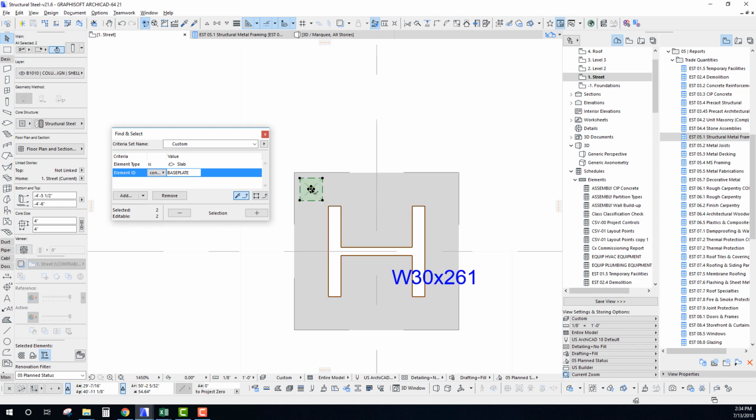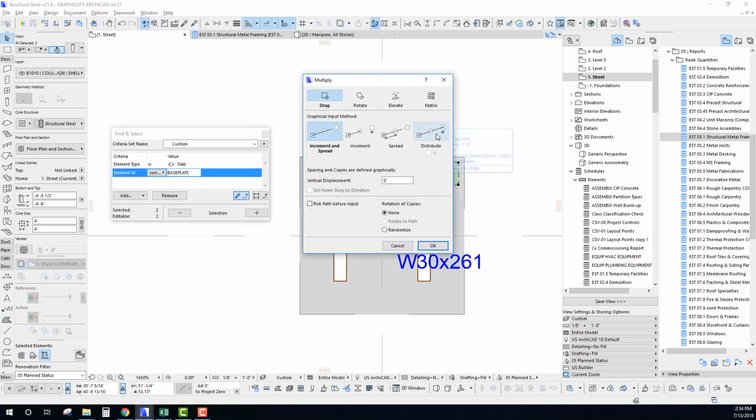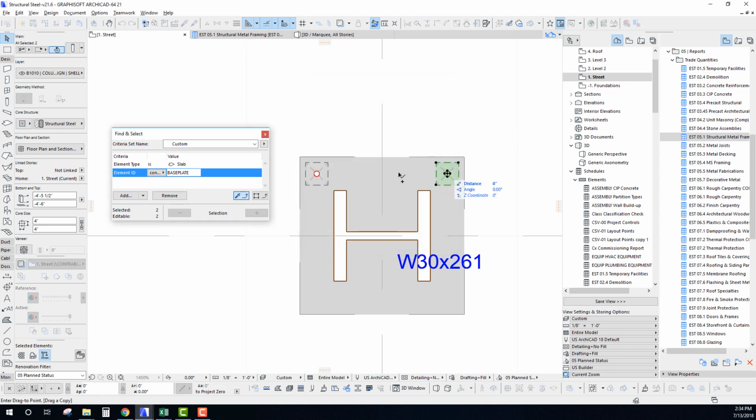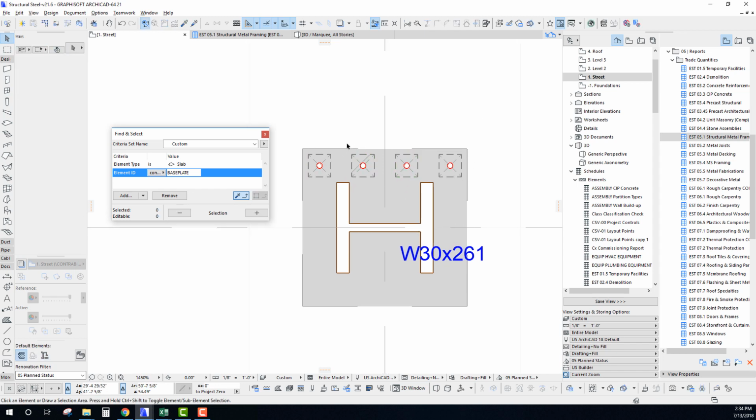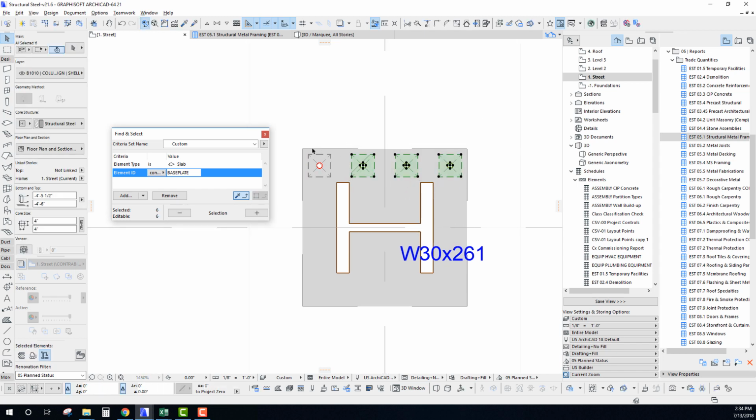And so let's just see if we can get a little creative in how we want to apply this. So of course, there's a lot we can do in terms of mirroring. So to get it going in this direction, I'd probably just mirror it. And then from there, I might just do distribute -1, create 2 copies, and go with it. So that's probably the quickest and easiest way. And from here, I could then just take these, take them all, mirror them in this other direction.